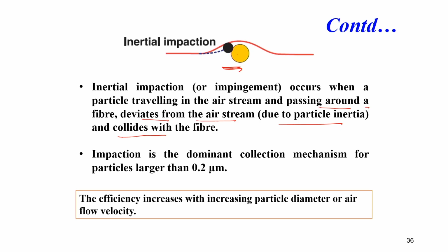Impaction is the dominant collection mechanism for particles greater than 0.2 micrometer, and its efficiency increases with increasing particle diameter or air flow velocity.